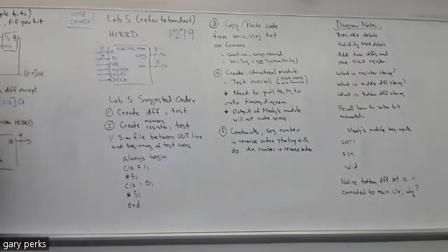You want a test case that makes sure it resets, right? So you set reset to 1, everything else is 0. You want a test case to make sure it sets. You want a test case to make sure that when it's loaded, or when enter is active, whatever's on the D input gets assigned to Q.